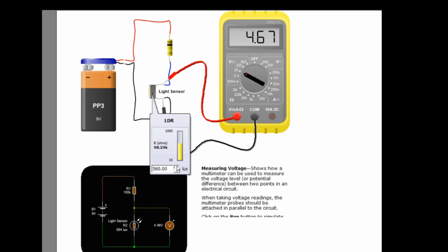Connect the probes. Connect the probes to the part of the circuit or component where you want to measure voltage. For DC voltage, red should go to the positive side and black to the negative side. For AC voltage, polarity doesn't matter. Ensure that the multimeter is correctly connected in parallel with the component or circuit to measure the voltage.